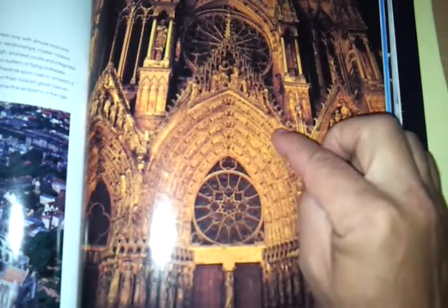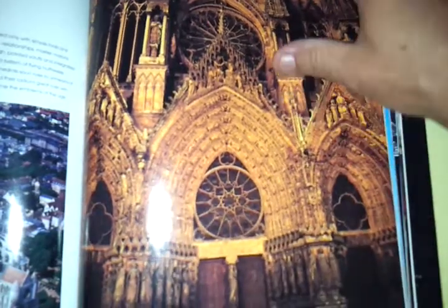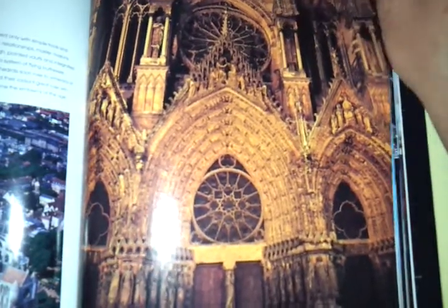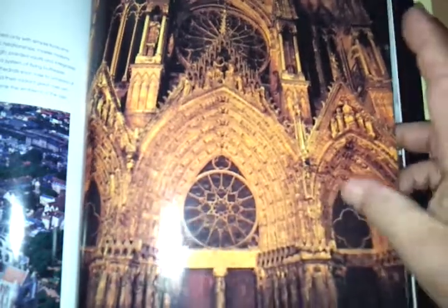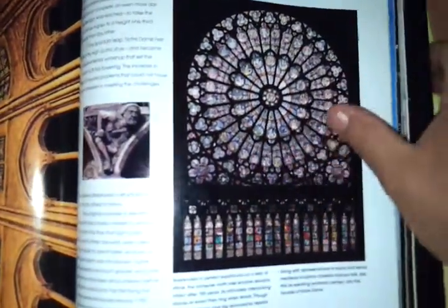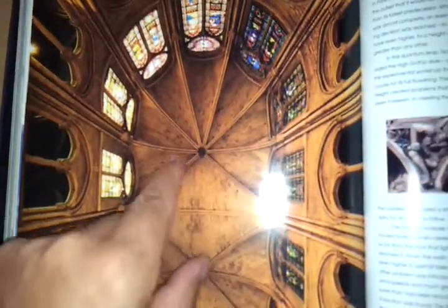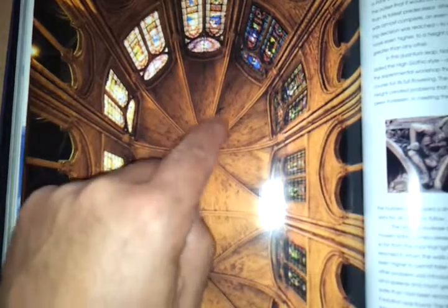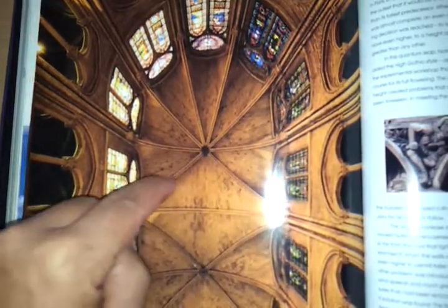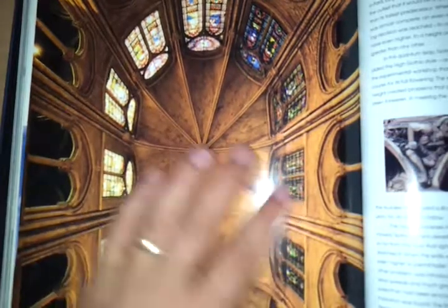Stone was used, still in compression, but light was allowed to enter into the building, and you can see that the building changes considerably because the buildings are lighter. With all these empty spaces, they can also be taller, and you can see the use of stained glass here, and I'll show you the roof structure. So again, the roof structure of one of these great cathedrals has a vaulted ceiling, which essentially are arches, and all the arches place everything in compression, and stone could be used to create these very tall, seemingly slender buildings.